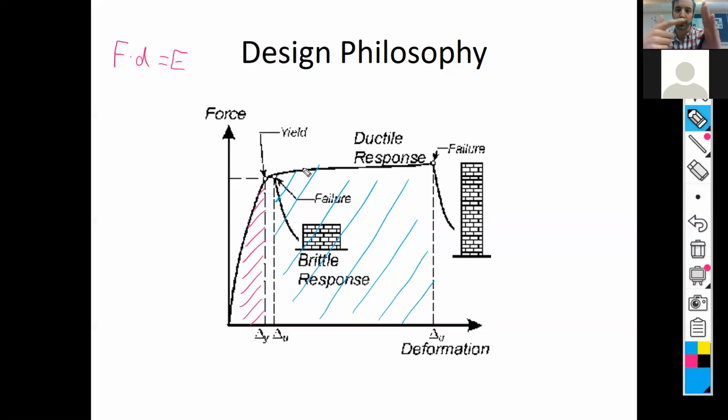The spring is going to snap. The same is true if I have a tall building and I deform it and release it: if the deformation is elastic, then it's just going to snap back and continue to shake. Now, if I deform it plastically and I release it, it's just going to stay there. All that energy I put into the deformation is not going to be transformed into vibration energy, but is just going to be dissipated.